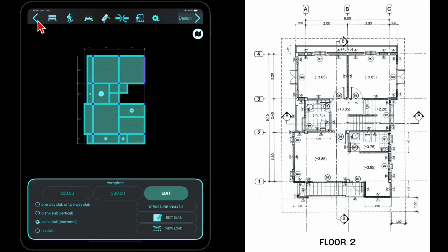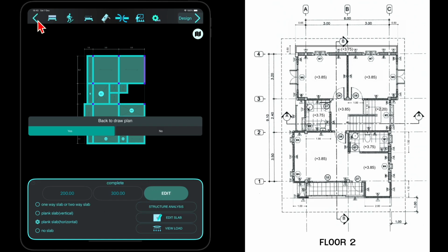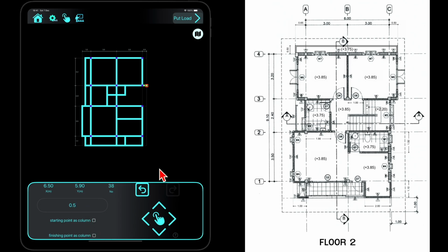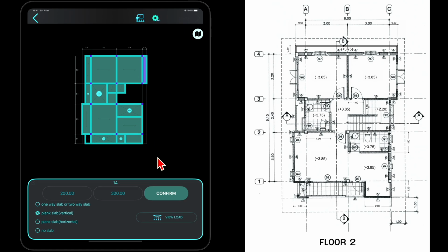If you need to modify the beam layout, you can return to the main screen. The previously entered data will not be lost, and you can continue adding the floor later. Once the floor layout is complete, there will only be a cantilever slab at grid line 4. Remember, whenever there is a cantilever slab or cantilever beam, always check for these precautions for safety.